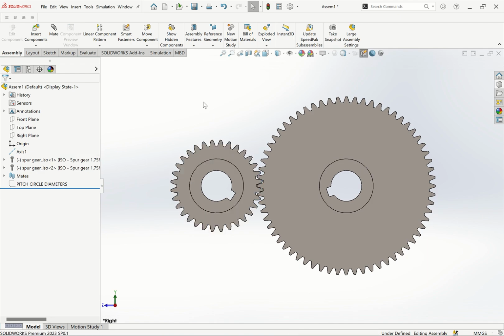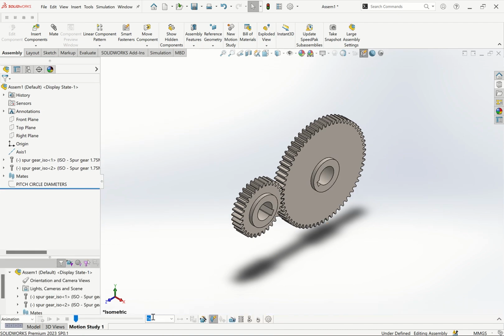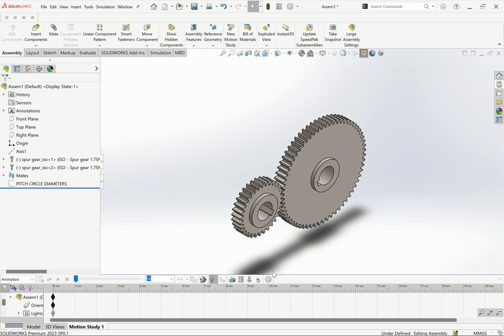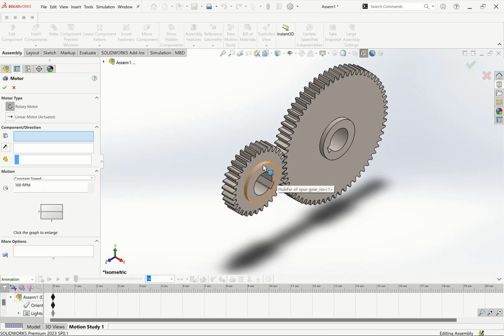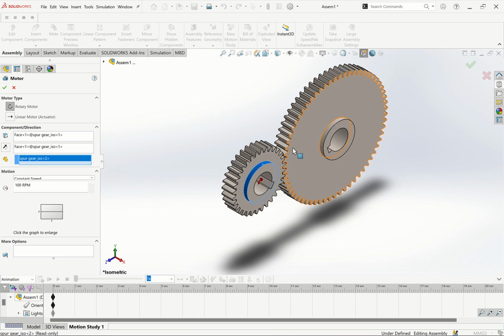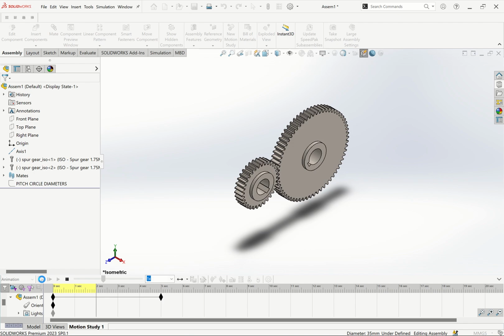So we have used Spur Gear to do mate. Then you can even put a simple motion analysis, a simple animation. You can put a simple animation. Maybe you put a simple gear here. You can say from this face, it's going clockwise. Component rotating to do maybe this one. You can put maybe at even to 1. For example, I want to just put symbol. Then you click OK. Then you click here, calculate. You can see when one is going clockwise, the other one is going anti-clockwise.